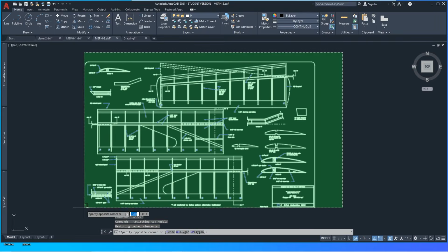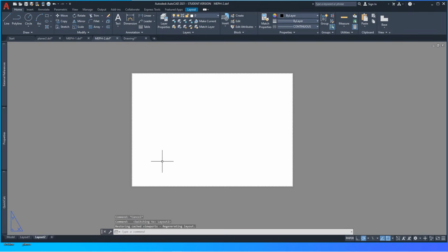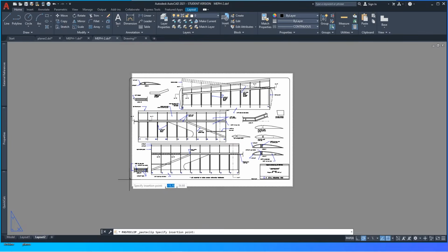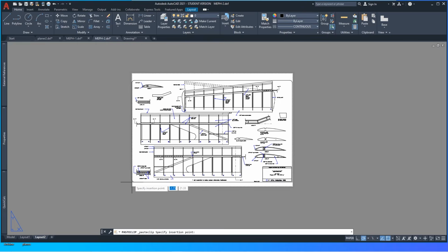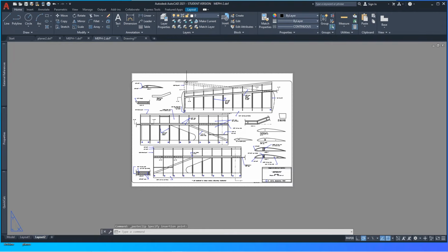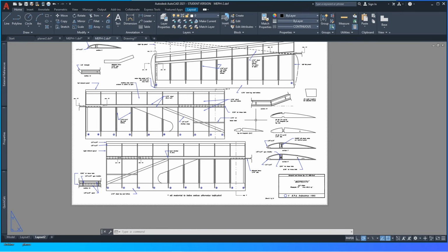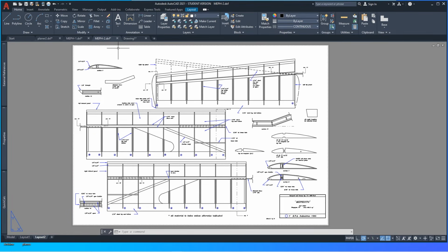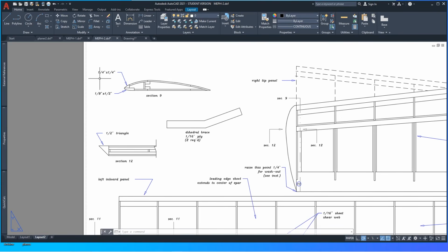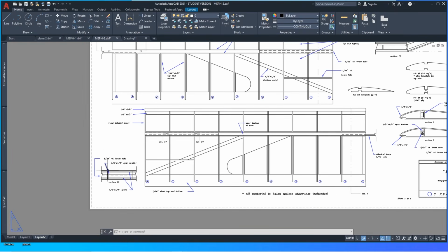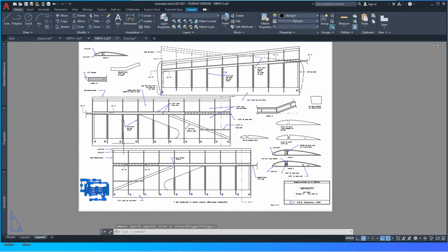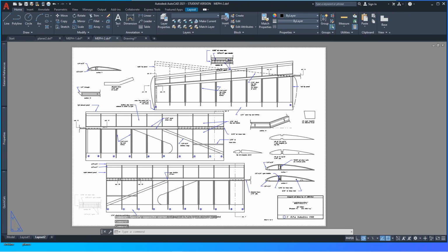Click OK, and now I'm going to copy and paste my drawing there, and that's the way I do it. I don't know if you have a different way to do this, but that's the way I do it. So I just copy and now I paste it here. I'm going to get rid of this frame. And now we have this ready to export. We know that it is in the correct size of A1. If we want to, you know, rearrange some stuff so it is not near the edge, so we know that it's going to print, you can do so. So for instance, I'm going to move this around here, somewhere around here.